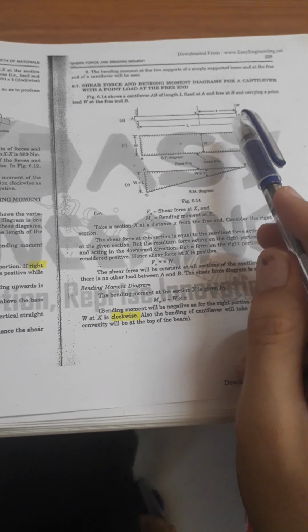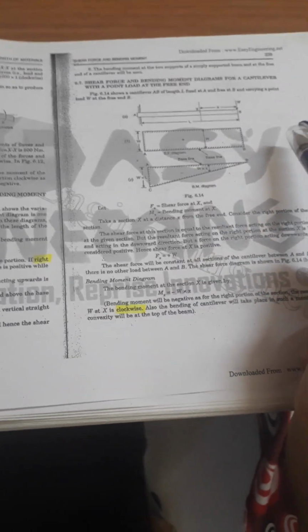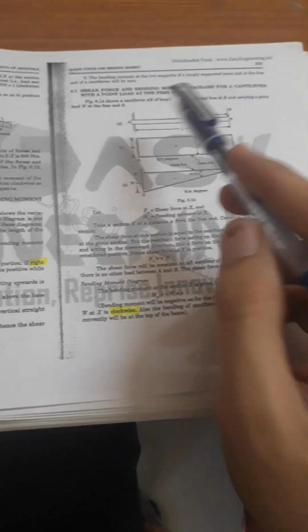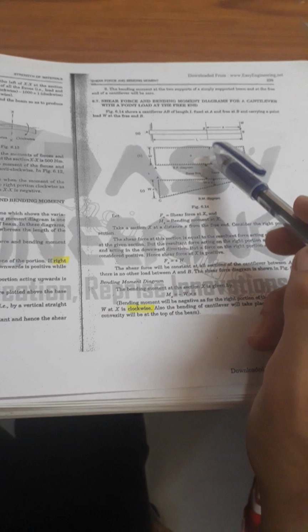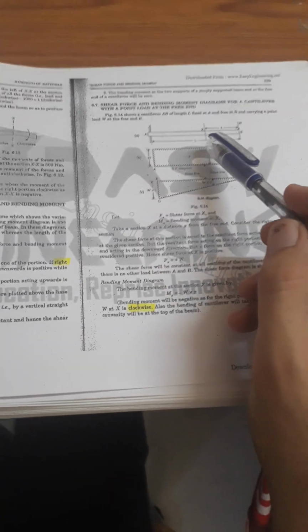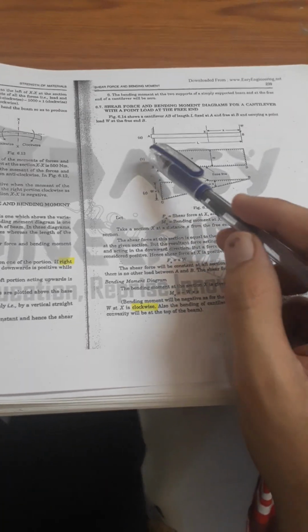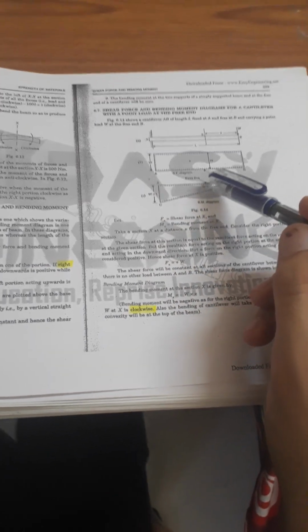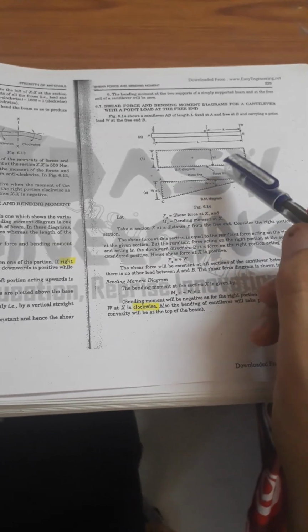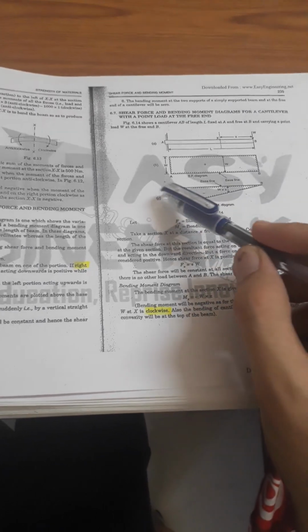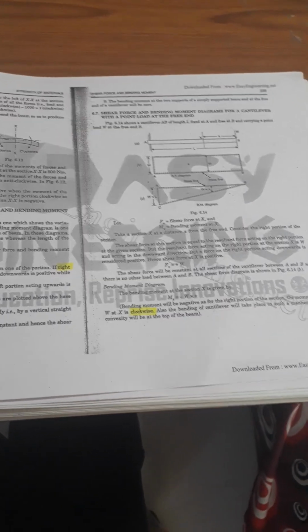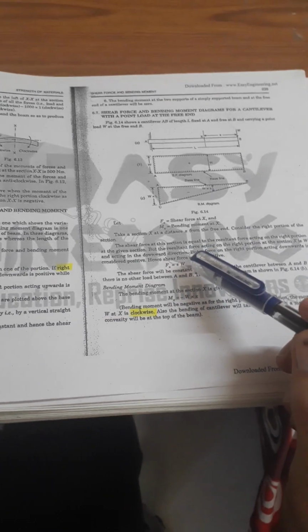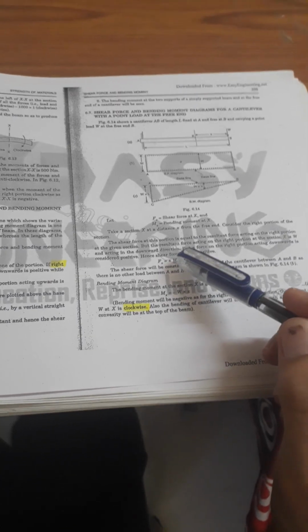This is the shear force and bending moment diagram for a cantilever beam. For example, here is the length L, the weight W, at distance X. The shear force is W, and the bending moment diagram is negative, with W into X, reaching W into L. How are these forces obtained? For example, here if Fx is applied,